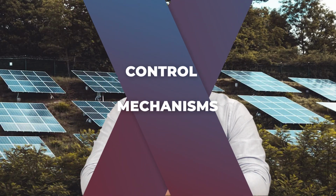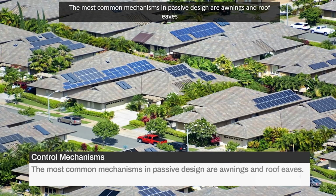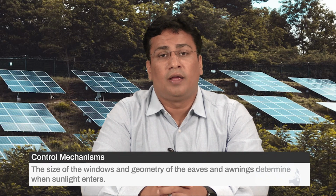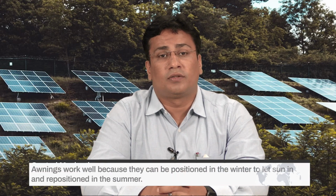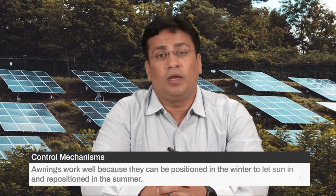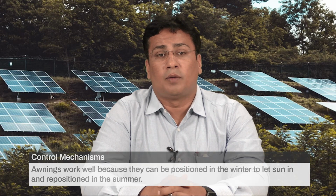The last one is control or control mechanism. Control mechanisms regulate when and how much solar energy enters a structure. The most common mechanisms in passive design are awnings and roof eaves. The size of windows and geometry of the eaves and awnings determine when sunlight enters. Awnings work well because they can be positioned in the winter to let sun in and repositioned in the summer.